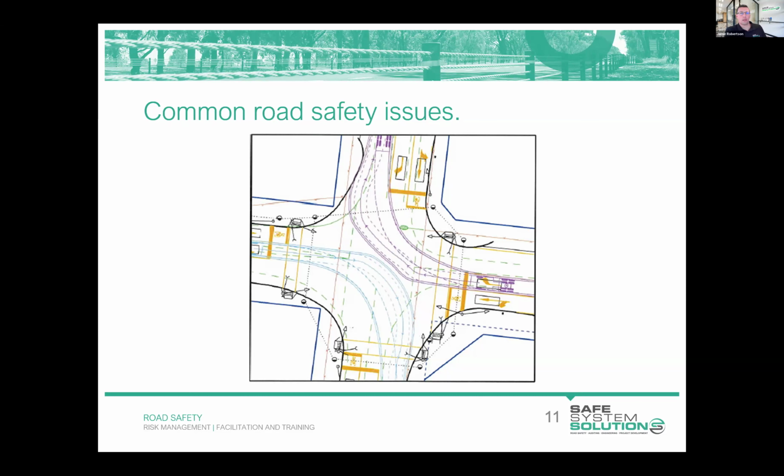Another thing that I'll point out are these little arrowheads that you might notice along this center line of the vehicle path. Basically, those arrowheads represent a decision point or a mouse click when using the software, a change in direction. So you can see quite a few of those little arrowheads on this purple swept path. So that's not an intuitive way for a driver to make that movement. You would like to see the turn made on a single radius, at a radius that accords with the Austroads guides.